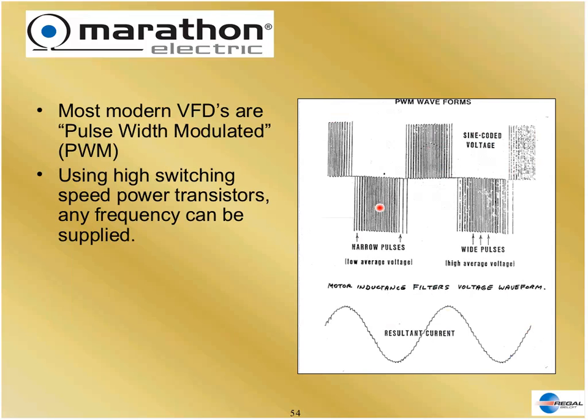The thicker pulses produce higher peaks on the line. Thinner pulses produce lower. Plus and minus, we are back now to a curve, just like we had before. Only this curve, and you can do this three-phase, by the way, there'd be three curves. But this curve goes up and down. It rises and falls. How many times it rises and falls per second is its frequency. With power transistors, I can give you any frequency.